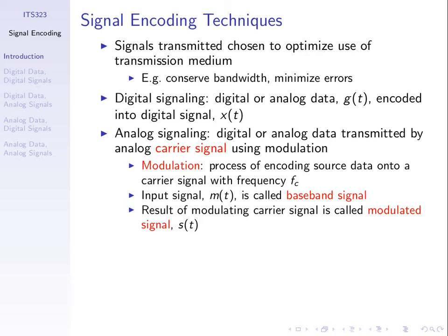We think of our digital signal as transmitting some voltage pulses. So if we have an electrical signal, we maintain some voltage at some level, let's say minus 5 volts and plus 5 volts. So maintain some voltage for some time period to represent one piece of information, and then a different voltage for the same time period for a different piece of information. For example, bit 1, bit 0.